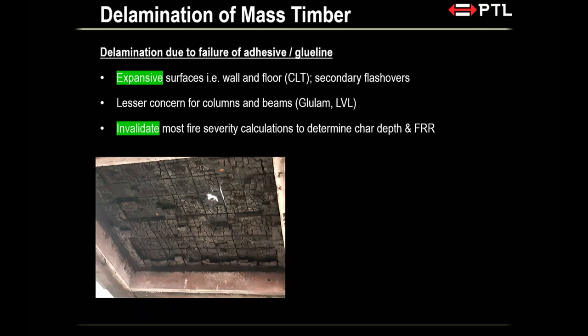Because if you come down and start blocking it up, yes, you maybe solve the traveling fire problem, but what about means of escape? Because you can't run through the fire curtain, right? It just comes down, you need somewhere else to go. And fire curtain is sometimes a bit tricky to detail as well. And what sort of fire resistant rating are you designing it for? A lot of them are 30, maybe 60. But the moment you get into 120, they become really hefty. And it's the cost as well.